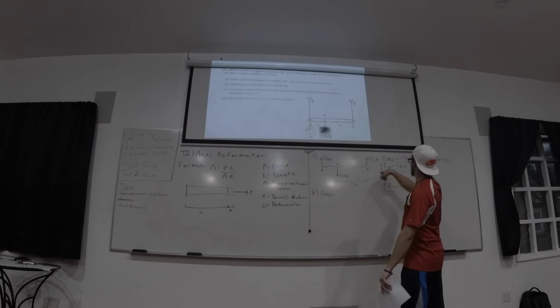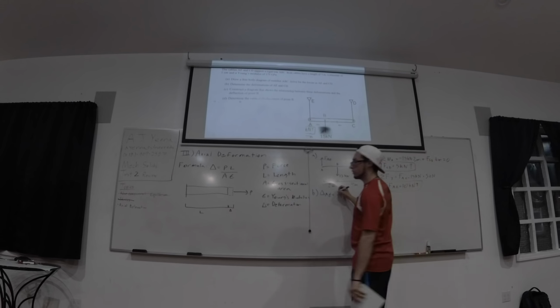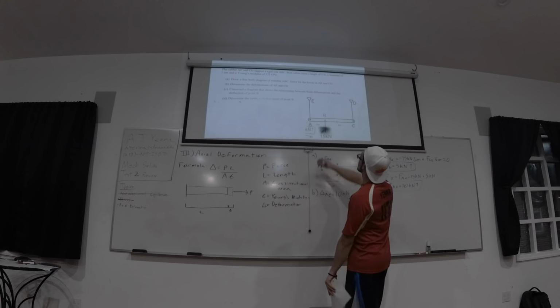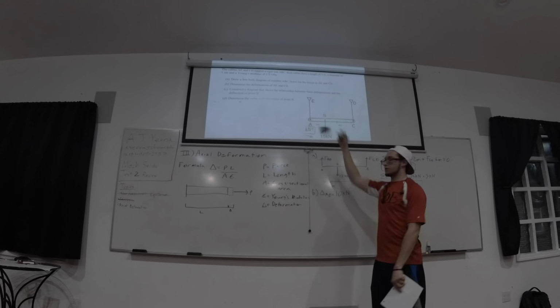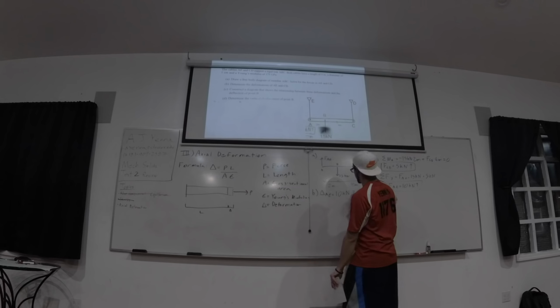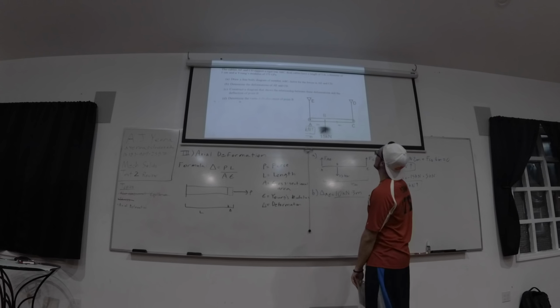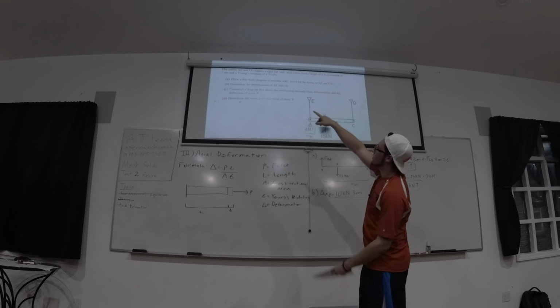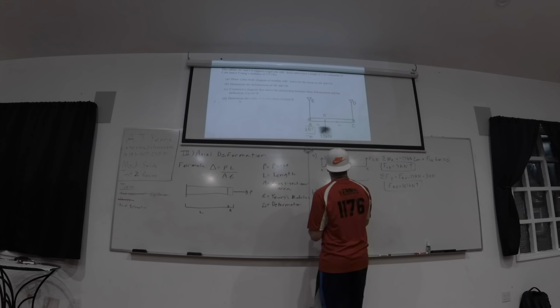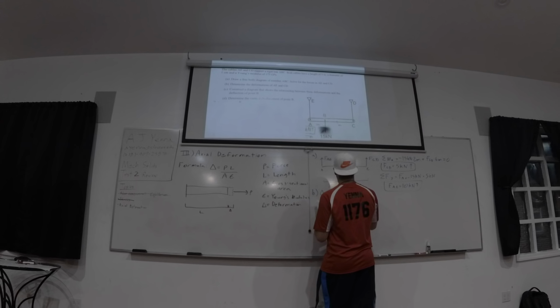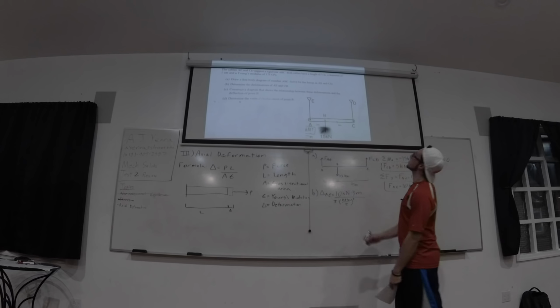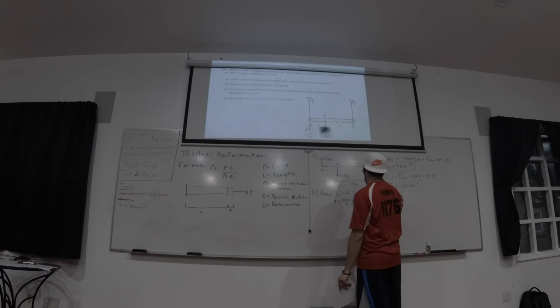So the force in AE, which we just found, is 10 kilonewtons, times the length, which is both of the cables at a length of 3 meters given, divided by the cross-sectional area, which has a diameter of 1 centimeter, so area is pi times 0.01 meter over 2 squared, pi r squared, times Young's modulus, which was given at 175 gigapascals.